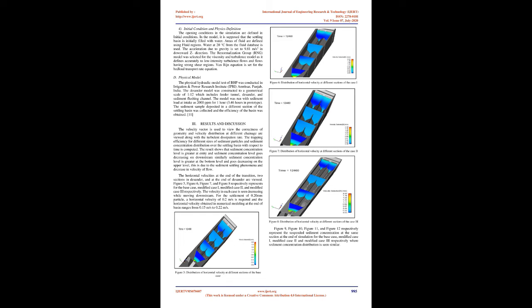B. Mathematical formulation. The equations of motion for fluids are solved with the volume of fluid, VOF, numerical technique. The Cartesian coordinates, x, y, z, system is used to solve the differential equations that are formulated with area and volume porosity functions. This formulation, called FAVOR, fractional area/volume obstacle representation method, is used to model complex geometric regions. 1. Governing equation. The main equations used in this simulation are the mass continuity equation, the Navier-Stokes momentum equation, and the sediment scour equations. The general mass continuity equation for incompressible fluids is as follows.